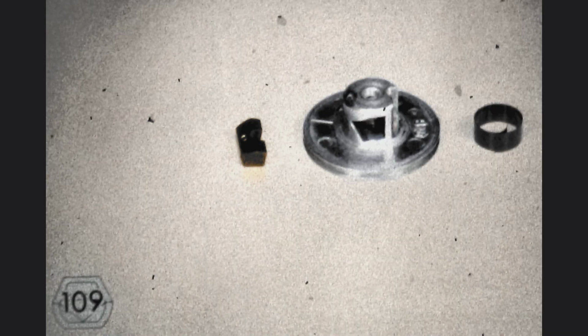Let us now disassemble the parts which constitute the rotate detent. The first part is the rotate pulley. Once we have removed the spring which fits around the hub of the rotate pulley, we can pull out a wedge, which in this picture is positioned to the left of the pulley. The set screw on the rotate pulley always presses against the wedge instead of pressing against the shaft. This way, we can very accurately position the rotate pulley and prevent any kind of burr or mark on the rotate shaft from interfering with the adjustment of the position of the element.